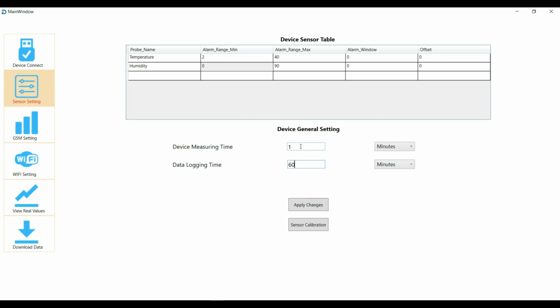For example, setting a few seconds for measurement of temperature in a room is not a suitable option as the temperature of a room may not change in a few seconds. Here we set 5 seconds for demonstration of live data and charting, but to extend battery lifetime, setting a short time period in normal applications is not recommended. When you are done with parameter setting, press Apply Changes.